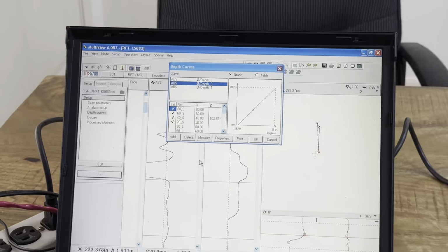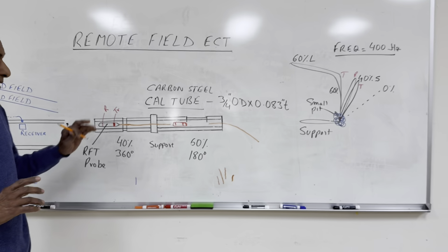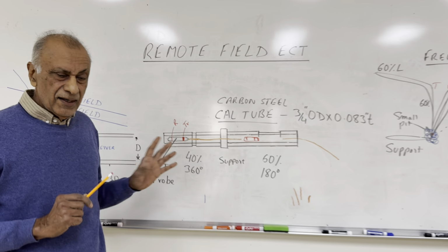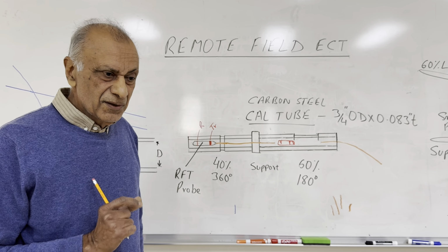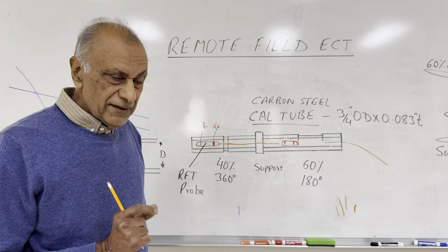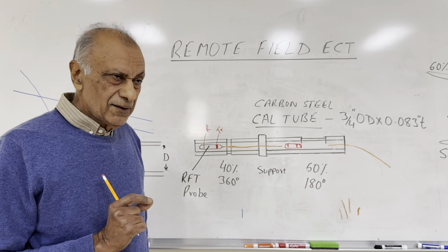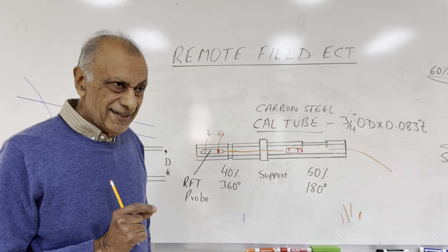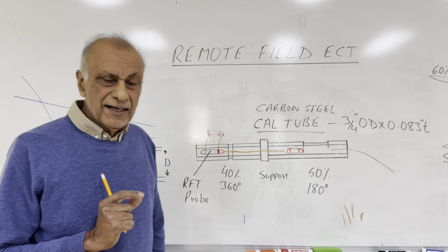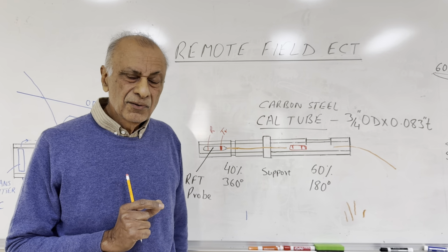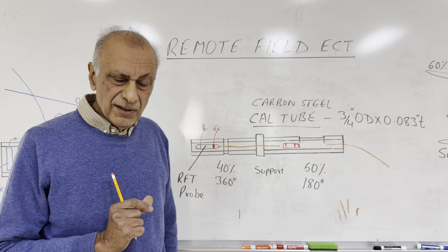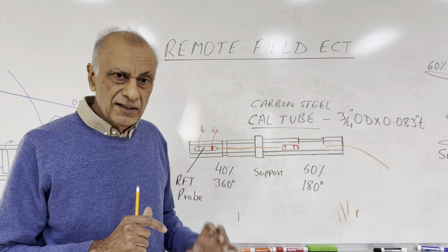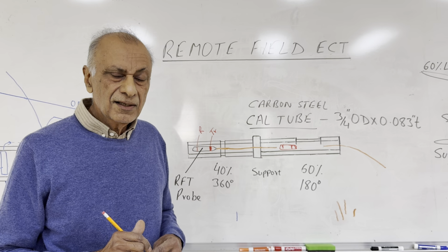So in conclusion, just remember, its technique is different than conventional eddy current testing. It's not as sensitive to small pits and holes as conventional eddy current testing. So remote field eddy current is a good technique, provided you know the limitations of this technique. The main limitation is that it's limited to wall loss, general wall loss.